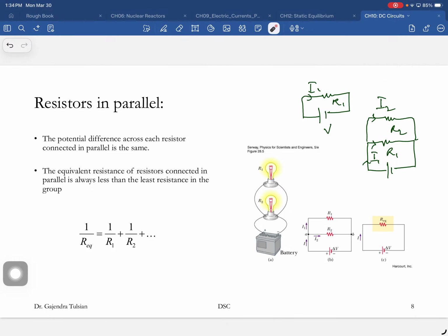Okay, so let's come here. Imagine this was not there. Then this would have been 1 plus 1 plus 1, 3 ohms. But you connected this guy in parallel to this guy, so his value reduced from 1. So there was 2 ohms here, and this is effectively less than 1. So R has to be less than 3.